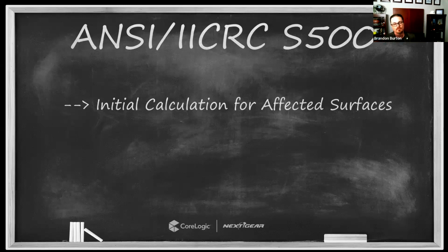The reason for that is because of many of the concepts that we discussed earlier in the webinar series. When we start a job, we're dealing with surface water and free water. These are the types of water that respond well to air movement. As we get towards the latter stages of the project, we get into something called the falling drying rate. We're dealing with bound water, and bound water does not respond well to air movement alone. It responds well to vapor pressure differences, which, by the way, is going to be our next topic of conversation next month: understanding vapor pressure differences and how to leverage that. So starting heavy and finishing light on air movement is the key to effective mitigation. The more we deploy that, the more effective we're going to be.